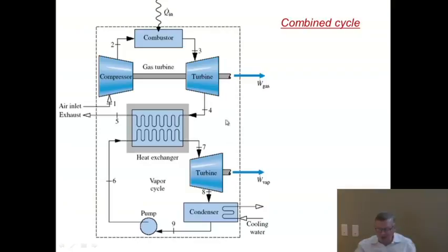Okay, so in a combined cycle, you exchange the boiler and the steam generator for, in fact, a heat exchanger that comes from a gas turbine. So you have a second cycle, a topping cycle this time, that takes in air, compresses from 1 to 2, combustion 2 to 3, 3 to 4, and it's the enthalpy in the air between point number 4 and point number 5 that gets transferred to the water, where it gets transformed into an enthalpy that goes between 6 and 7 in the water.